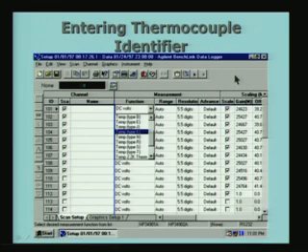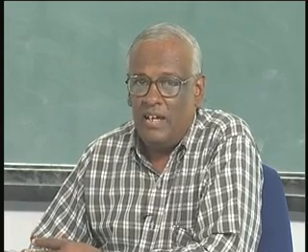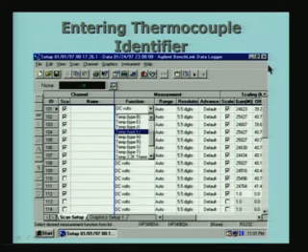Of course, the data logger costs a lot of money. This data logger, for example, costs about 50,000 rupees, and you can see the number of channels. The number of channels can be 16 or 64, 128 and so on. Different data loggers come with different number of channels, and as I indicated in the last lecture, the data logger also can plug into the USB port of a PC nowadays. The one which I have shown here does not do that, it has to be connected through an interface, and it has got its own controller and so on, but the new ones come with USB. You can communicate with the computer using the USB port directly. So, it is very plug in and play, as they say.